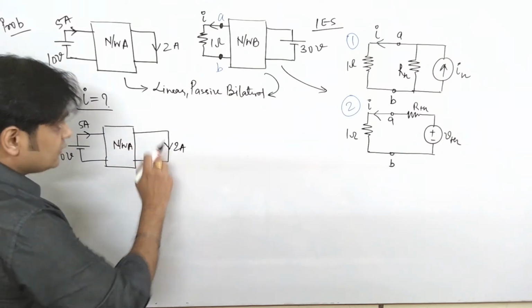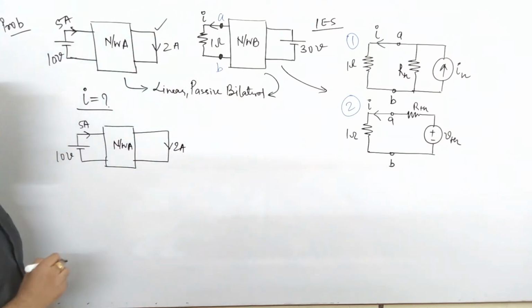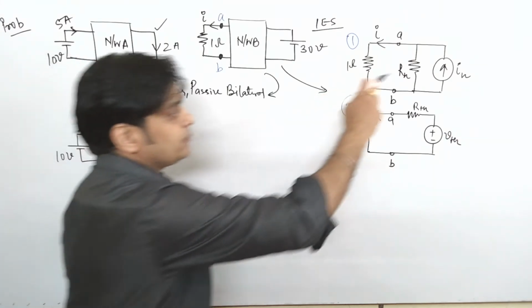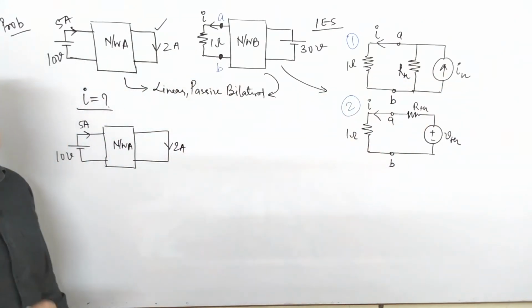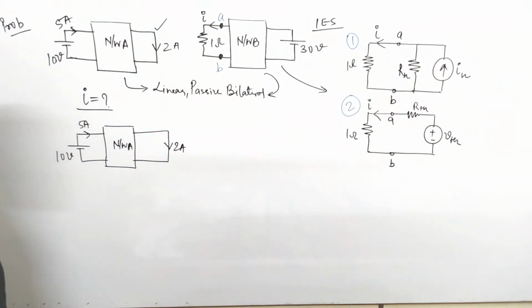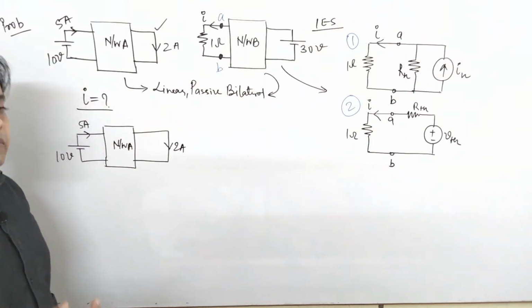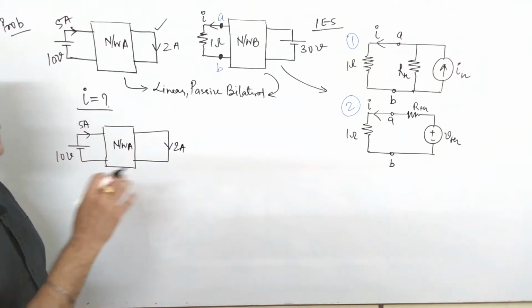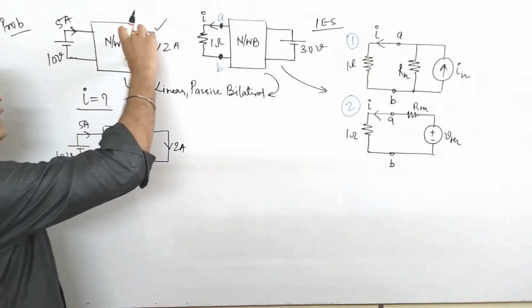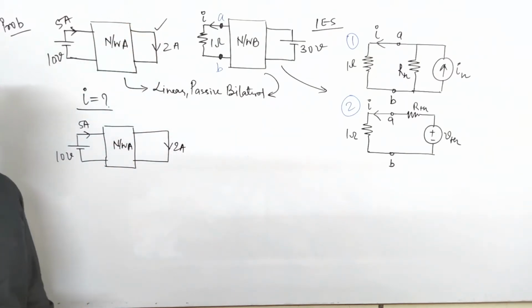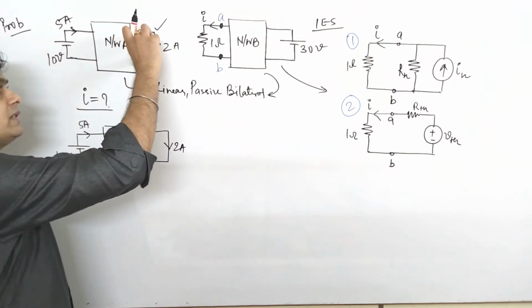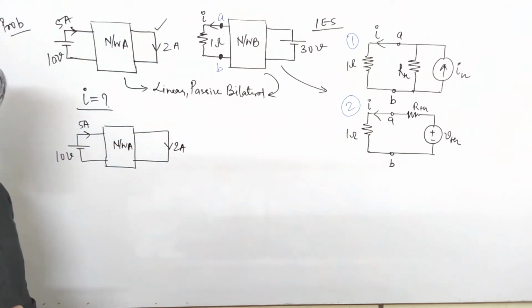So whenever you find a short circuit branch here, simply apply the concept of Norton's. Why? Because we have to find the short circuit current, and short circuit current is found when the two terminals are short circuited, so it will be easier for us to find that condition. And if you find an open circuit voltage present here, simply apply the concept of Thevenin's theorem.